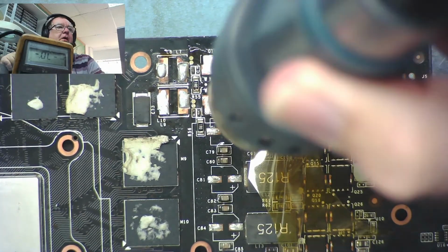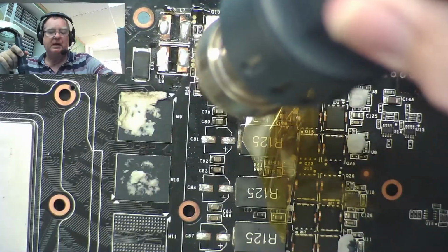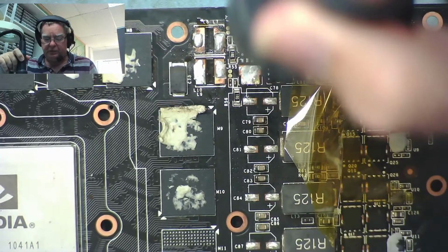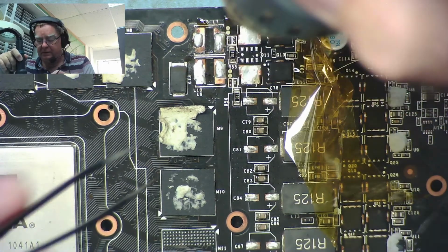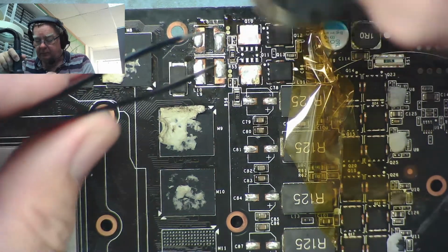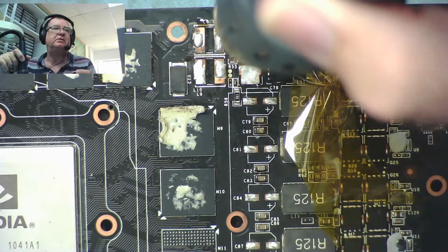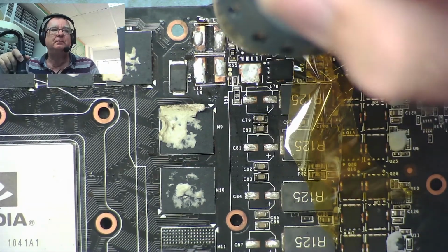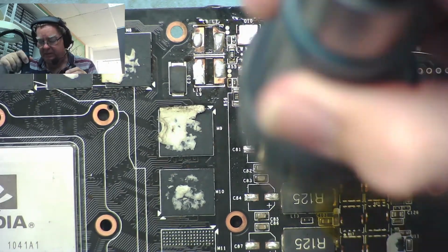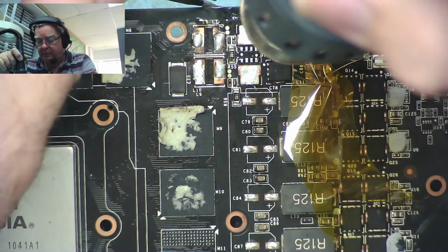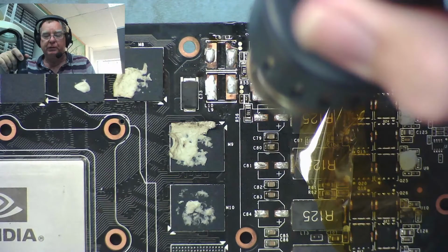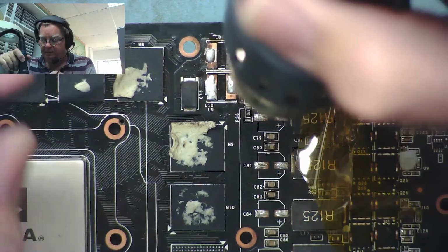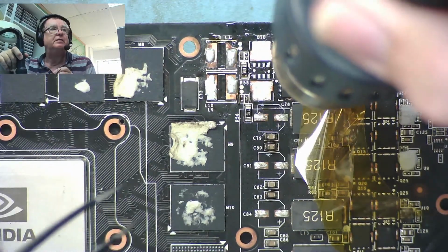I hope you can understand the reason I'm checking these. It's because I have no understanding of why that chip has blown up, basically. I can't see any reason. I mean, sometimes things just fail, but it seems a bit strange. If I can get these MOSFETs cheap, to be honest, I'll probably order some new high side and low side MOSFETs, even though they test okay, if they're not expensive.